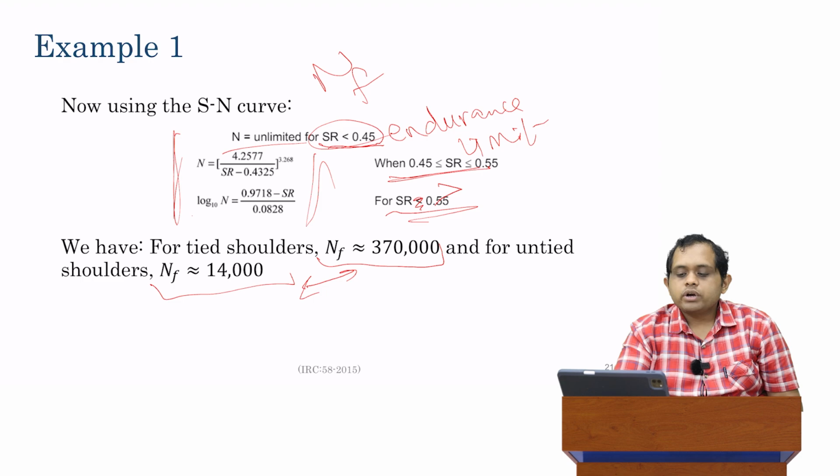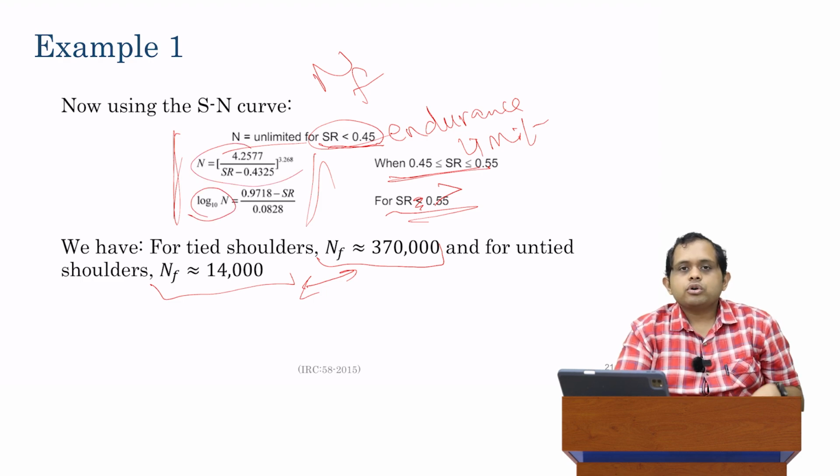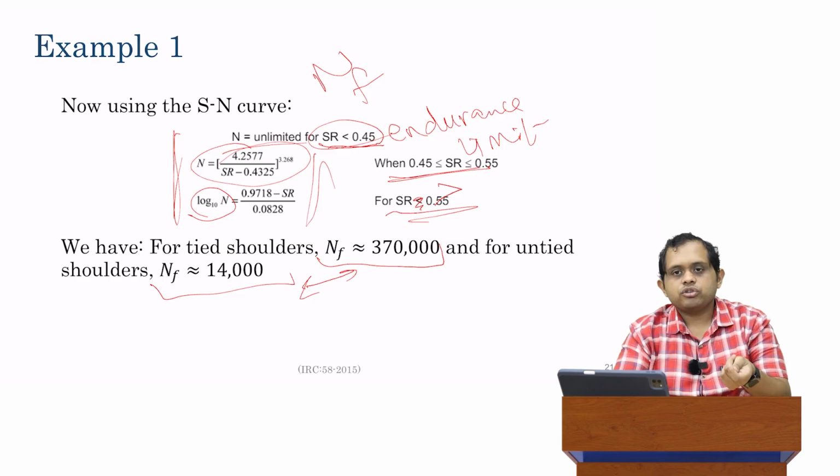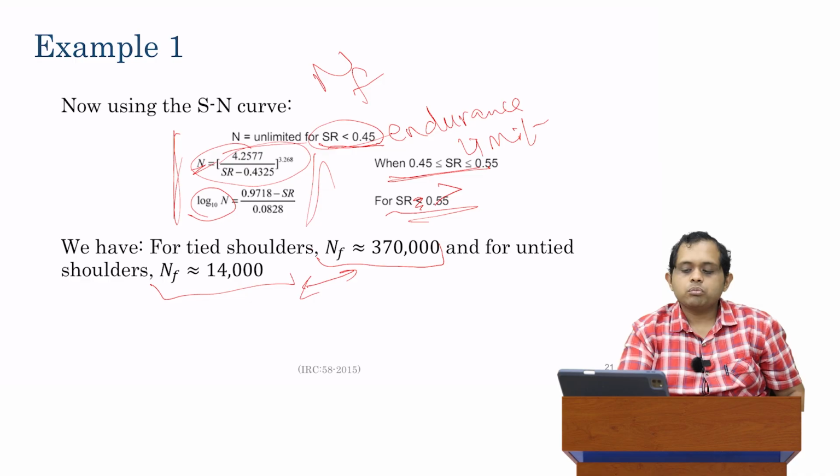It's very typical. If you look at the equation, these are logarithmic. So algebraic changes in stress ratio, that is, a small change in stress ratio, on algebraic orders, 0.1, 0.2, that sort, give you logarithmic changes in the number of allowable repetitions. That's how the equation is built. So don't be surprised when you see more zeros popping up.